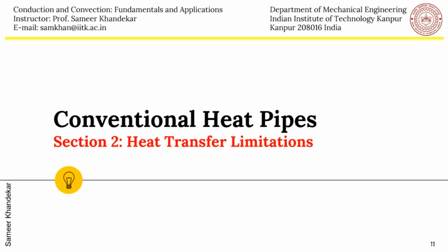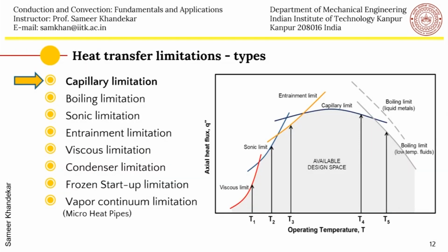As we have been discussing, the operating temperature of the heat pipe for any given fluid ranges from close to the freezing point up to the critical point. We have seen the figure of merit, and we have also seen that it differs at different temperatures. So it depends on at what temperature you want to take the heat out. Suppose you use water and you want to maintain the temperature of the electronic component at 50 degrees.